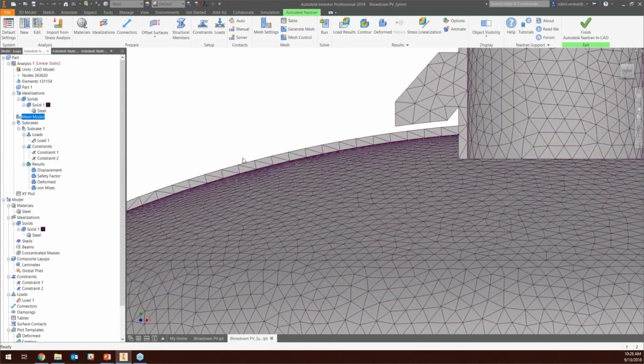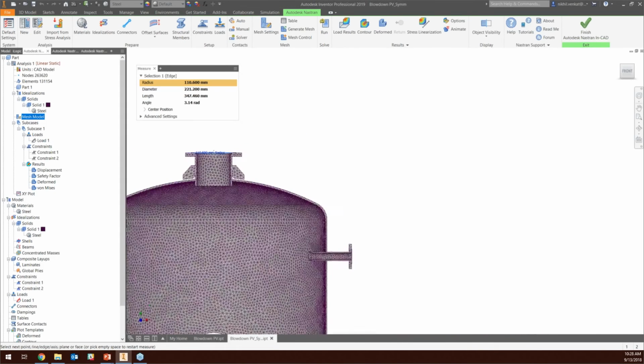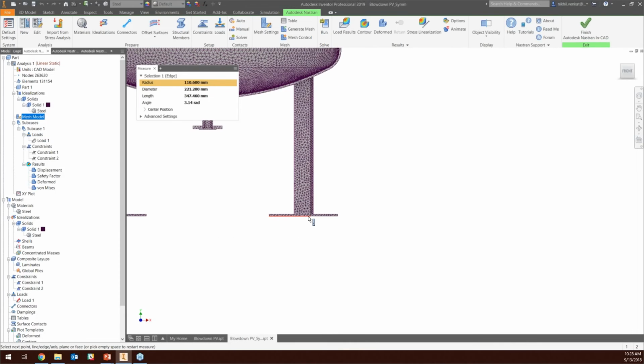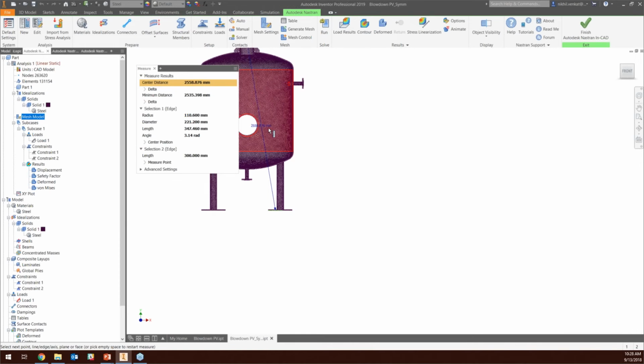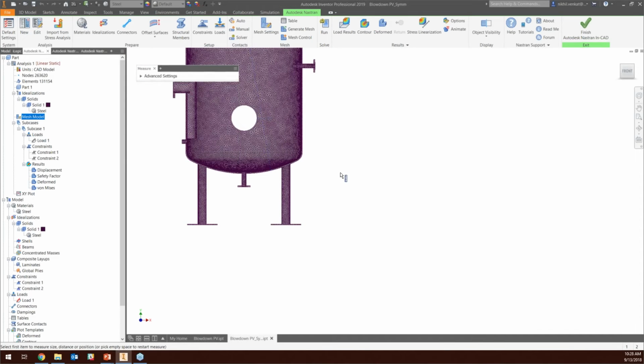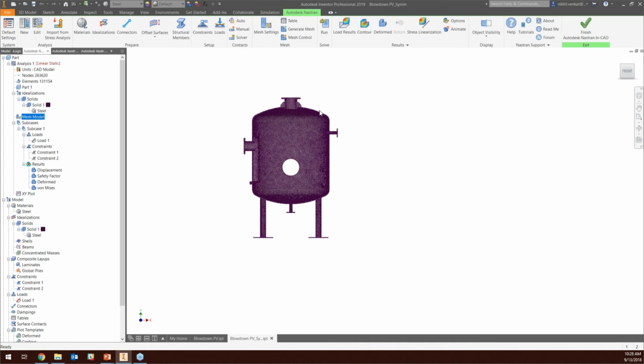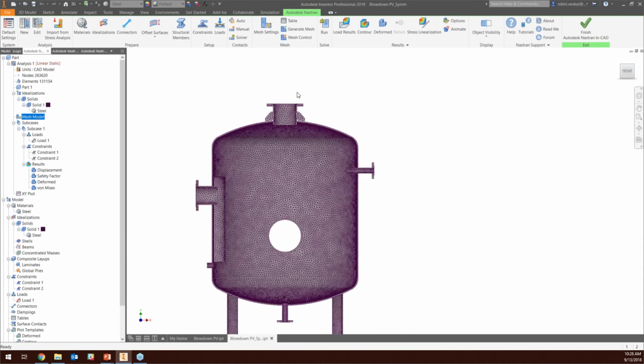When you're looking at solid structures or whatever, in regards to meshing, any areas of note is what I like to say in the particular model itself. Any areas of note where you're expecting something weird to happen, or you're expecting a very large difference between one side and the other side of a particular surface, you're going to want more elements, right? But for here, we're expecting pretty uniform deformation and stress across the entire surface. So you don't need to necessarily increase the mesh number for that.